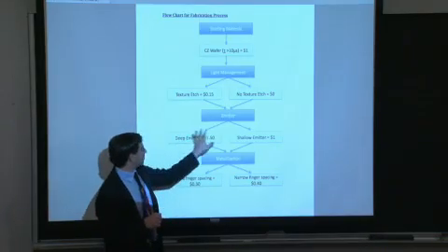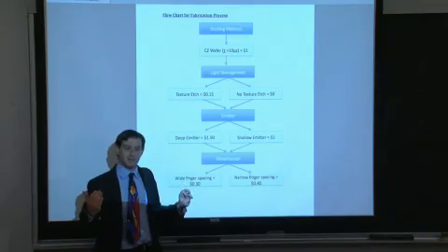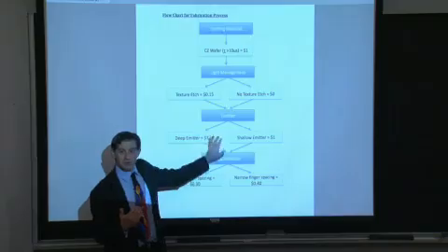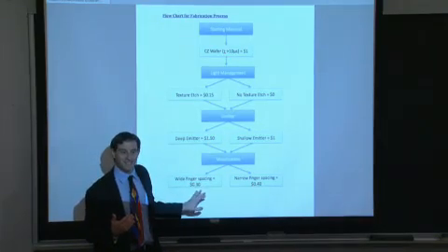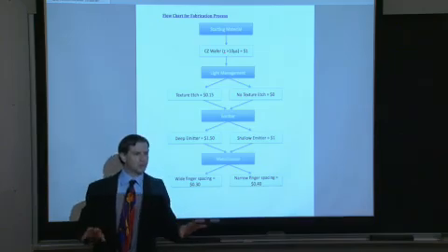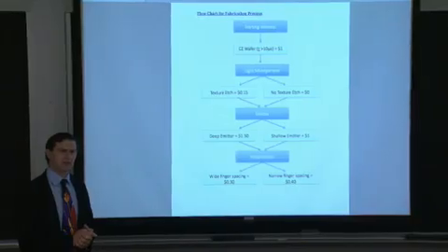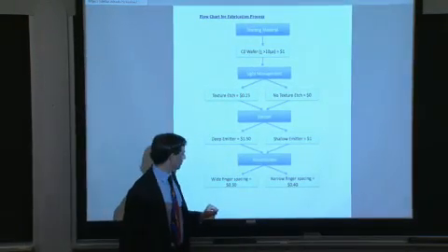Whereas, if you decide to go for a deep emitter, it stays longer inside of the furnace because the phosphorus will diffuse deeper inside of the device. Your blue response will be poorer, but you'll have less risk of shunting. So it's up to you to use all of the tools that you've assembled so far to make a value-based judgment whether or not it makes sense to go with this or that, as your selection choice.